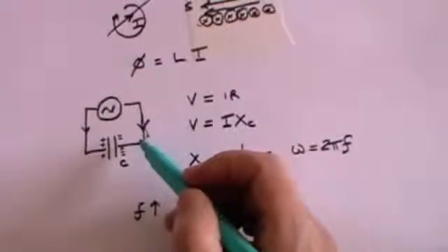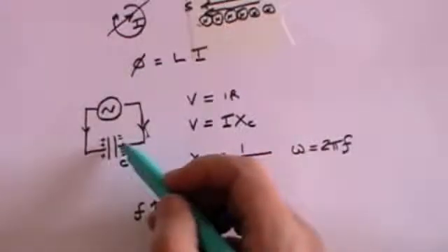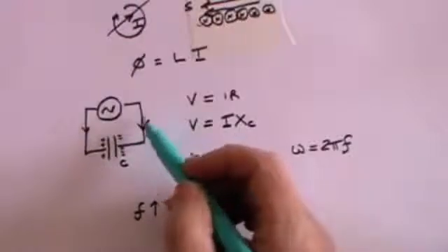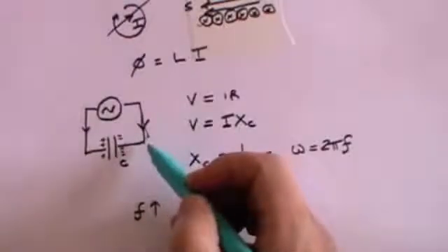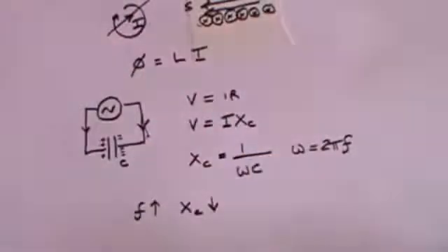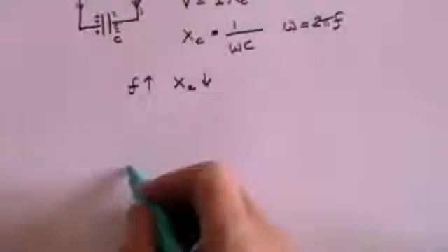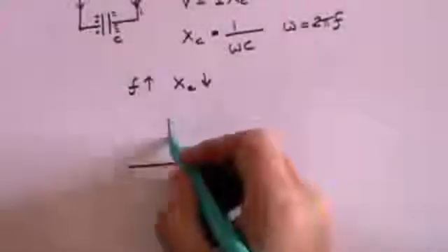So the higher the frequency, basically the less time there is for electrons to build up on this plate and impede the other electrons that would like to try and join them before the current changes direction. But there is something else that is noted by experiment, and that is that if you plot the voltage